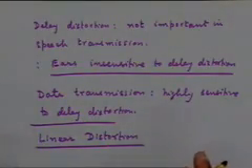One important characteristic of linear distortion is that the existing frequency components of the message signal get treated differently by the channel, either in terms of their attenuation characteristics at different frequencies or in terms of delay characteristics at different frequencies, right? So that's linear distortion.